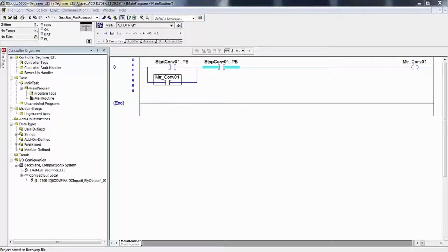This feature, concurrent engineering, also allows you to discover additionally needed I/O devices that would not be apparent until the program is written and you discover that you do not have the device on the I/O sheets of the drawing set. In other words, if you wait until the drawing set is complete and then you sit down and create all your tags, alias them, look at the descriptions on each I/O device and then alias it to that module defined tag, then start writing your program. And as you're writing the program, you realize that you need a photo eye on a particular conveyor and it needs to go in a particular spot on a particular I/O card.